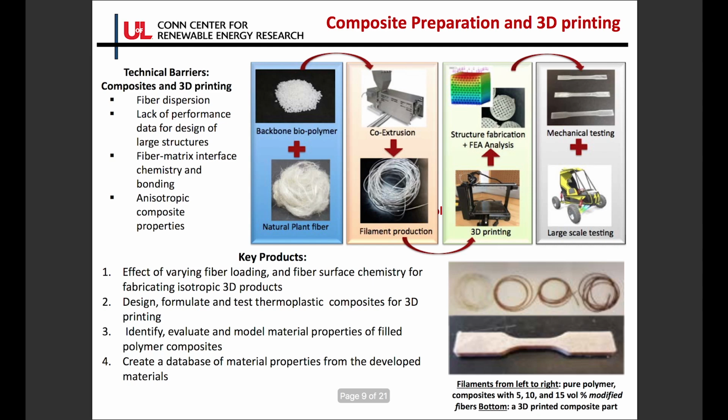We know that for 3D printing, there are different things we can do. The challenges are essentially fiber dispersion. How do we make sure that in a polymer material, the natural fiber is dispersed properly? And the fiber retting process that we have chosen gives us more opportunities in terms of removing the anisotropy. We need to make sure that isotropy is there, with uniform properties in the machine direction as well. We minimize the anisotropy using some of these modifications we are doing.